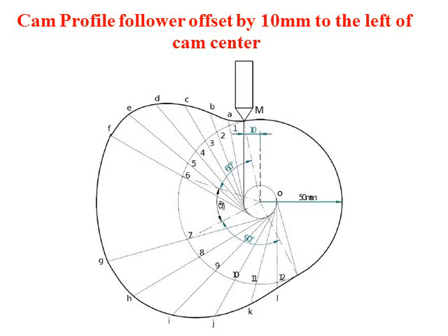So next, go back to the displacement diagram. There, measure the distance 1a using a compass. Transfer that distance to the cam profile by taking 1 as the center and cutting an arc. That way we have to transfer all the points. After transferring all the points, join them by a smooth curve.